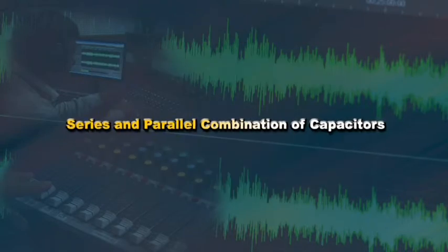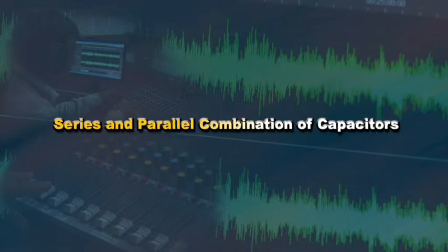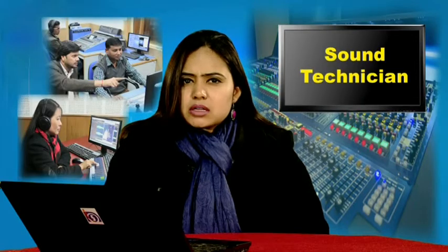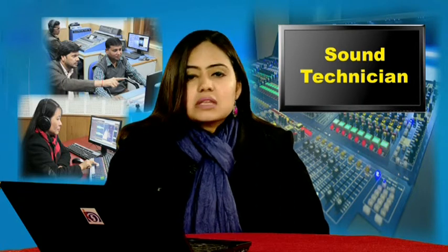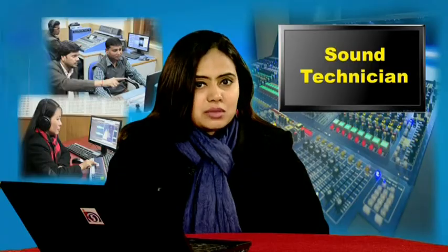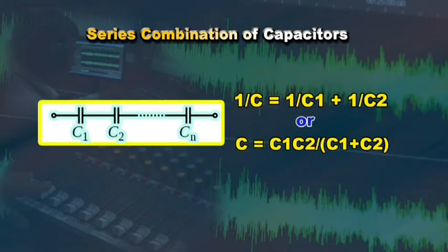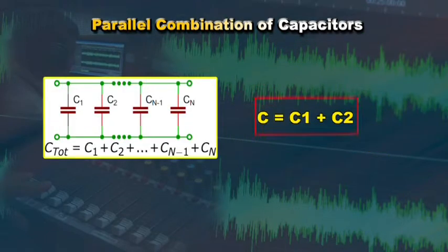There are also series and parallel combinations of capacitors. In order to get a required value of capacitor as per circuit design, both series and parallel combinations are commonly used. The resultant capacitance of capacitors C1 and C2 in series is expressed as 1 by C equals 1 by C1 plus 1 by C2, or C equals C1 into C2 by C1 plus C2. In case of parallel combination, it is expressed as C equals C1 plus C2.